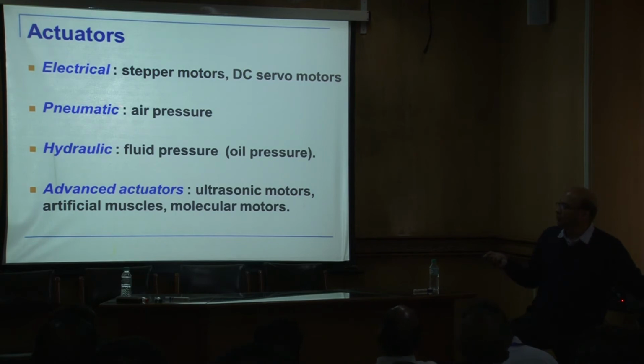The gripper is normally pneumatic, essentially because this piston cylinder mechanism for a pneumatic system is safe. So if the robot were to hit something, okay, if you have a motor, like you have a gear, this is not back drivable. You cannot drive it backwards. So if it hits something, something will break. Whereas a pneumatic system, a piston cylinder can just go back. So a lot of the robots today, which we call safe robots, are pneumatically actuated. Okay. So all the robots interacting with humans and things like that, a lot of them are pneumatic actuated because they are safer.